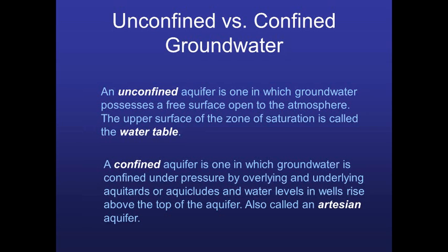And so let's say the water table is at 12 or 15 feet below land surface, and the aquifer comes up to maybe 5 or 6 feet below land surface. So part of the aquifer is dry, or only partially saturated, and the water table starts at, again, 15 feet. That's considered an unconfined aquifer because it has a free surface. It has a water surface, so to speak, that's open to the atmosphere. And so at that point, the pressure on the water system is atmospheric pressure.